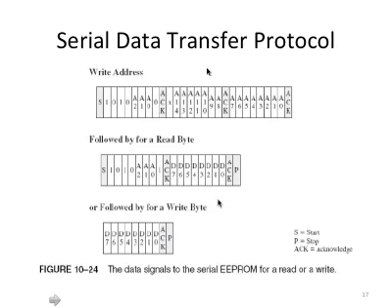Well, before the data comes out, these are the control bits coming from the master device that initiates this read operation, usually the microcontroller that wants to read this content. So again, it sends out this 1010 to identify the EEPROM chip: I want to access the EEPROM chip, and I want to access this particular one. Then that chip will respond with the real data, coming out of the chip one bit after another because this is a serial bus.